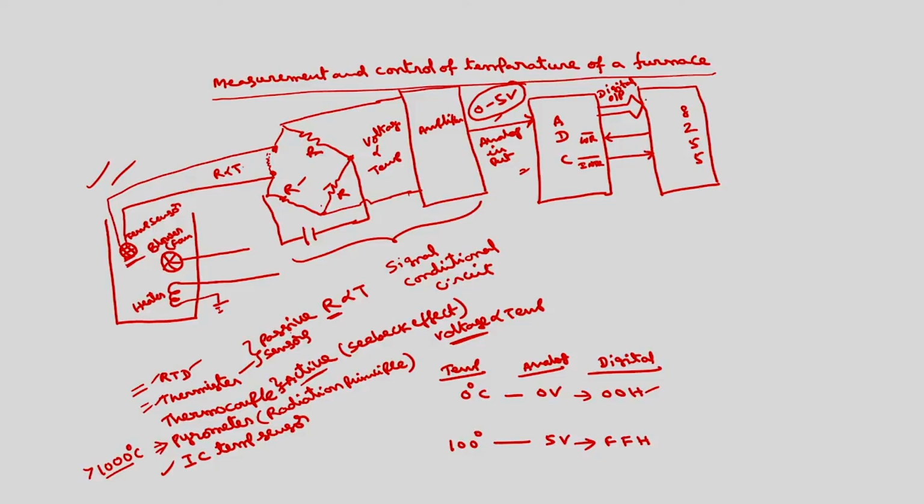This we are connecting to port A. This we have connected to PC3 in our earlier example. This we have connected to PC7. As we have discussed in the last lecture, in order to start the conversion, this WR bar should have a low to high transition. We have to apply a low to high transition at WR bar.